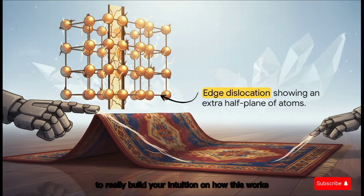To really build your intuition on how this works, imagine a massive heavy rug lying flat on the floor, but it has a wrinkle in it. Instead of trying to awkwardly drag the entire heavy rug all at once, you can just push that single wrinkle across the floor until the whole rug shifts. This edge dislocation acts exactly like that moving wrinkle. Pushing this tiny flaw through the crystal is the primary mechanism that allows metals to permanently bend, which engineers call plastic deformation, without snapping in half.